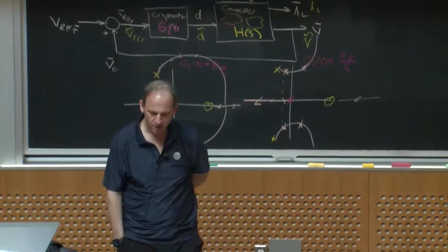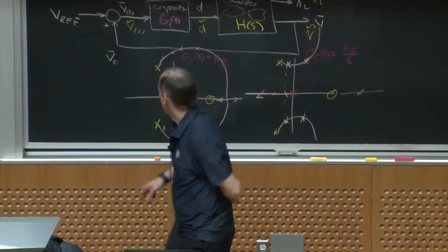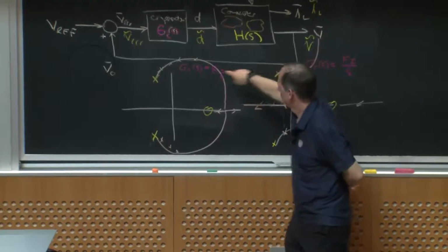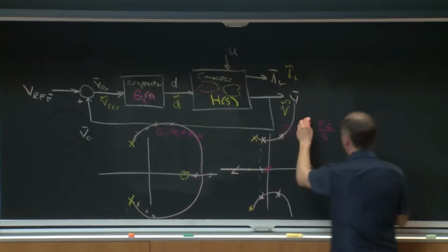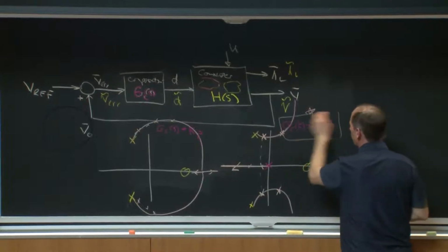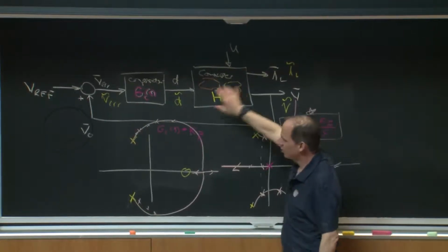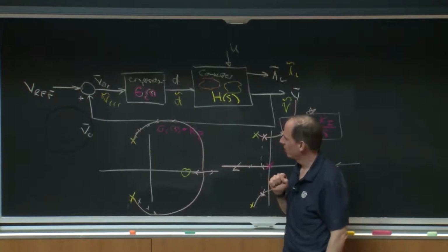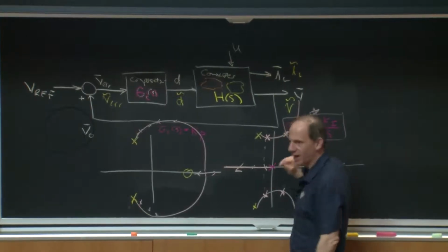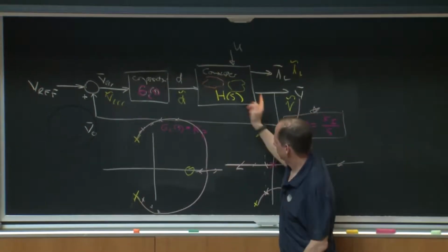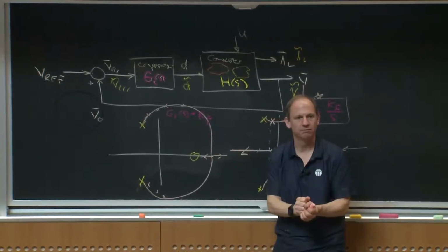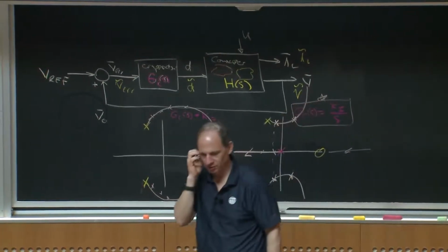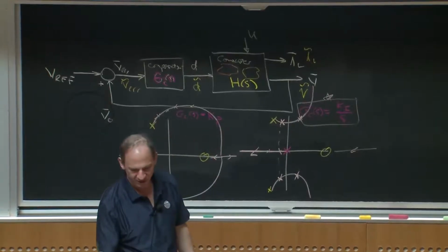What I'm going to do is let me put this system in a closed loop. I'm going to use a compensator. I'm going to use an integral controller. Okay? And I'm going to use my plant dynamics there. And then for different values of Ki, I'm going to take the closed loop. I'm going to find the closed loop pole locations. Then I'm just going to plot them. Okay? And I'm just going to do that, physically in MATLAB.